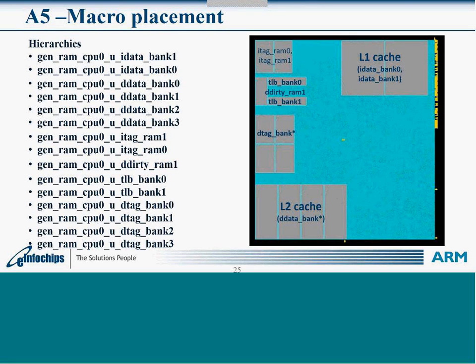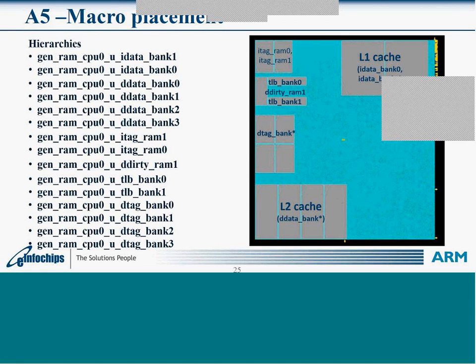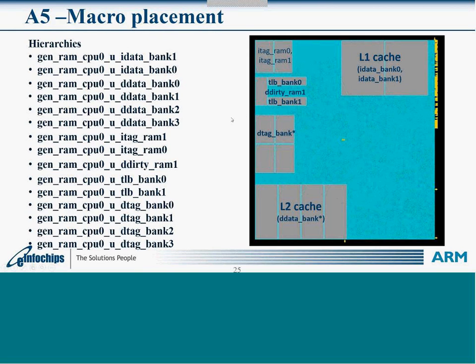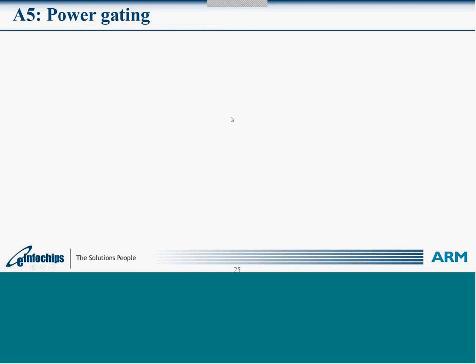If you divide it into different banks, we really gain some performance, basically speed. So we did a couple of benchmarking analyses before choosing these macros, and we tried different aspect ratios and different floor plan experiments, and then we fine-tuned the memories, and these are the final ones.